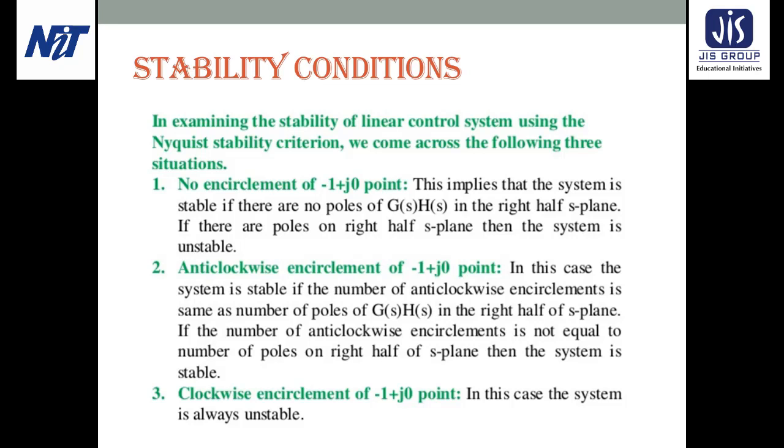And in other words, if the contour in the S-plane encircles more zeros than the poles of Q(s) or F(s) in the counterclockwise direction, then the corresponding locus mapped in the Q(s) plane will encircle the origin N times in the counterclockwise or anti-clockwise direction.